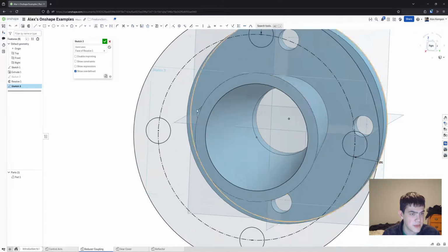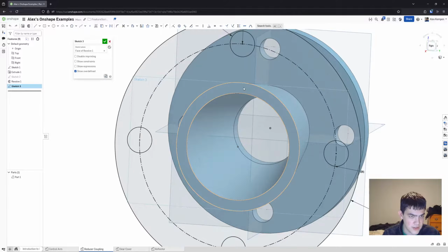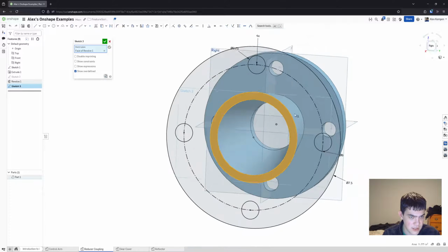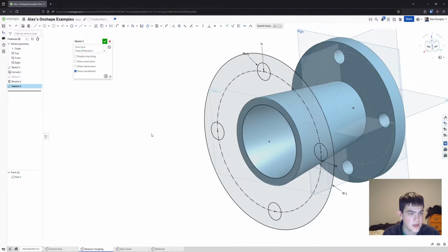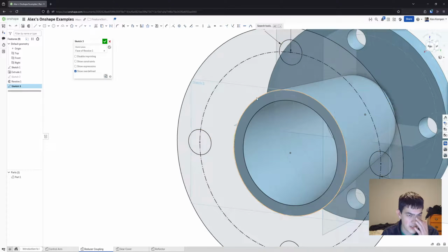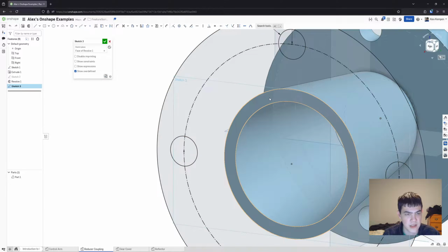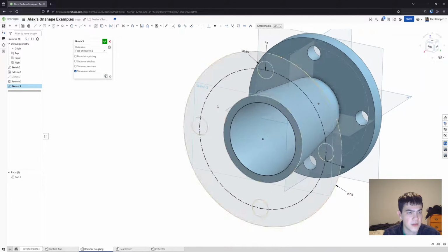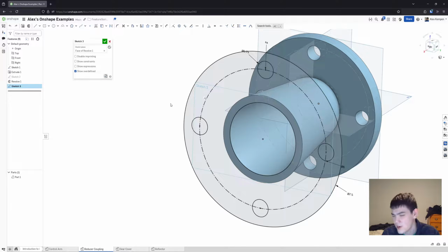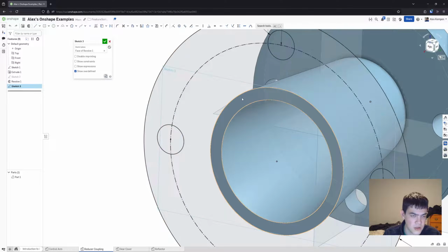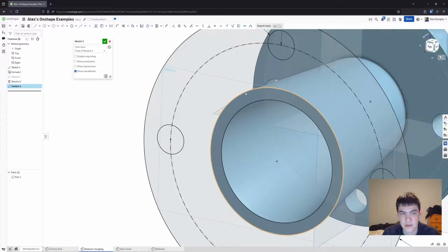So if I go back to my sketch, you can see here when we selected the sketch, we're sketching on this face. And so that causes the sketch to imprint on it. And so this edge here is actually splitting our sketch and making it into two separate faces. And so sometimes that behavior is helpful. More often than not, it's not. In this case, it arbitrarily divides our sketch into two regions, which doesn't really make sense.